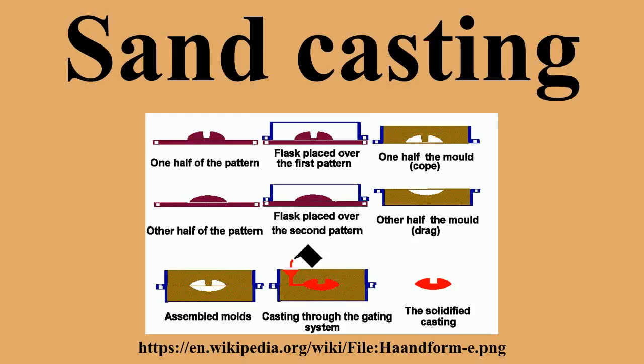Mechanized sand molding. The first mechanized molding lines consisted of sand slingers and/or jolt squeeze devices that compacted the sand in the flasks. Subsequent mold handling was mechanical using cranes, hoists and straps. After closing, the copes and drags were coupled using guide pins and clamped for closer accuracy. The molds were manually pushed off on a roller conveyor for casting and cooling.